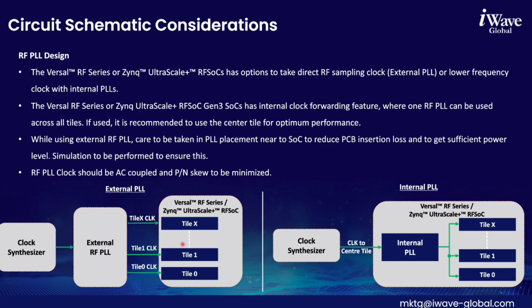We have two options: either we can use an external PLL or the internal PLL. Versal RF and RFSoC devices support both options. When we have very high performance requirements, we can use the external PLL and give the clocks to each tile. For most other applications, we can use the internal PLL itself.